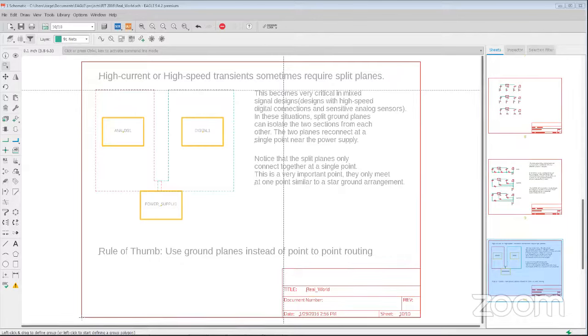Now, Jorge, there have been instances when I've done support where users will attempt to have an analog ground and a totally separate ground used for digital on the schematic itself, and join them at one point in common within the board layout. Is it really necessary to do it that way, or could they just run with ground with the same name and then position them in the appropriate place on the board in groups?